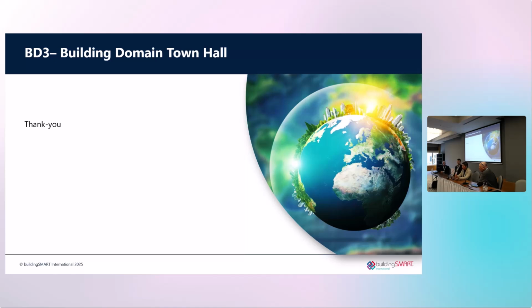So we simply came back to IFC space and mapped it with IFC space, but there had to be a separate space for each floor. But you need to build the whole thing, like the elevator shaft, which should be a shaft. So you need to group them together with an IFC zone, because you can cover it with an IFC zone. So you need a chance to say these spaces are part of a whole zone and the whole elevator shaft.